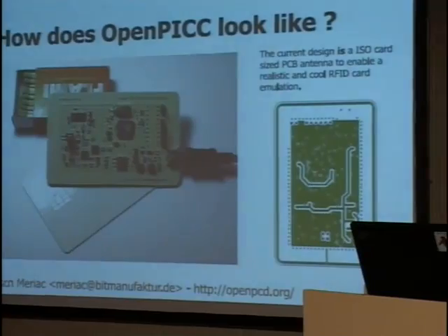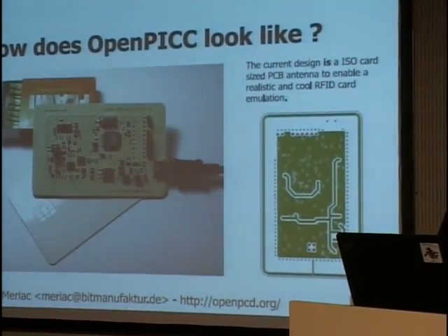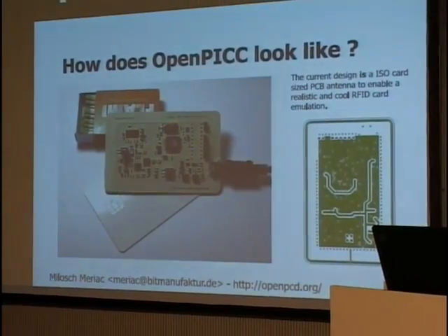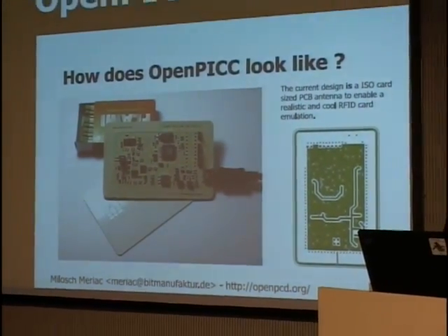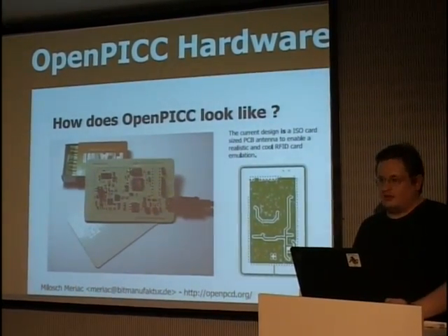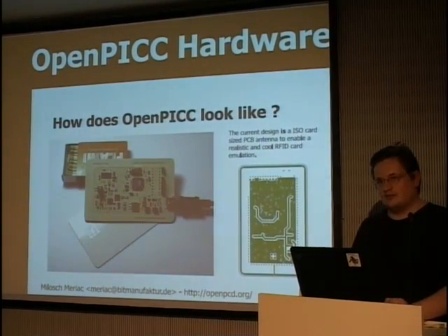maintain such tight timing, you definitely want to use assembler from time to time, for example if you have a high frequency interrupt routine where you want to do some strange stuff. You want to do it in assembler, and then a JTAG interface helps greatly. For example, if you're unsure that your code hasn't trashed internal registers, you can stop it at any time, read out a register, and let it keep running.